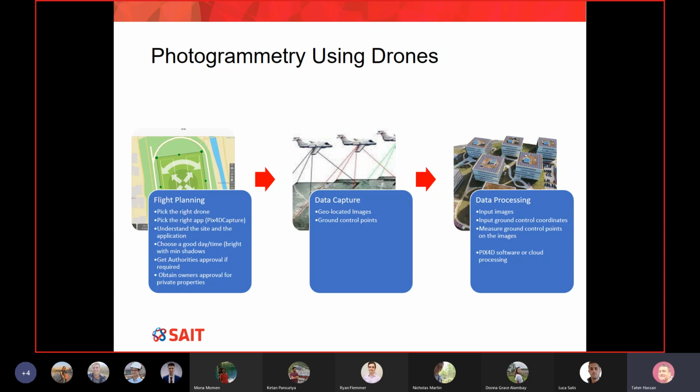In this case, the fixed wing drone really works very well because it can fly for a longer distance, but it doesn't rotate as easily. Think about how easily the fixed wing drone can take a turn and go back to a parallel line. It has to go on a radius because you cannot stop it. While a quadcopter stops in the air, then you can turn 90 degrees and come back along the next line. So it depends on your application. You must pick the right drone.